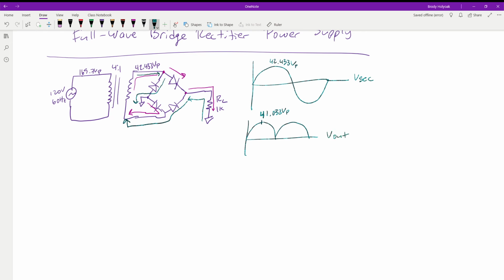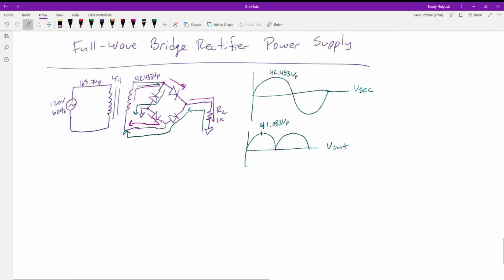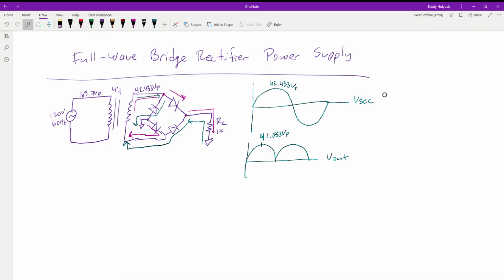Because it's the full wave rectifier, and in this process with those 2 waves coming and going, they're going to basically be adding together on the same point. And they're going to come in and get us this higher voltage out. So before, with the previous one that we saw, the max voltage that we had on this thing was about 20 volts. We had 20.5 volts was the max we could get out with just a full wave. When we use this bridge rectifier, even though we're going through an extra diode, it creates the pathways and the option for us to get double the voltage out.